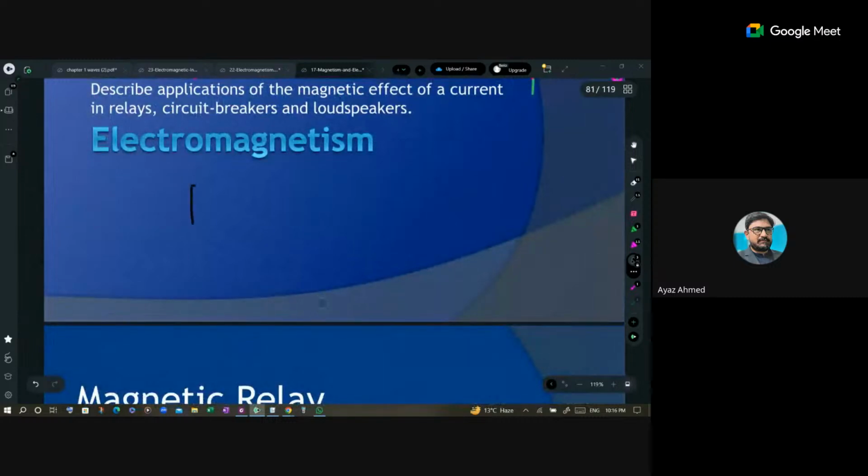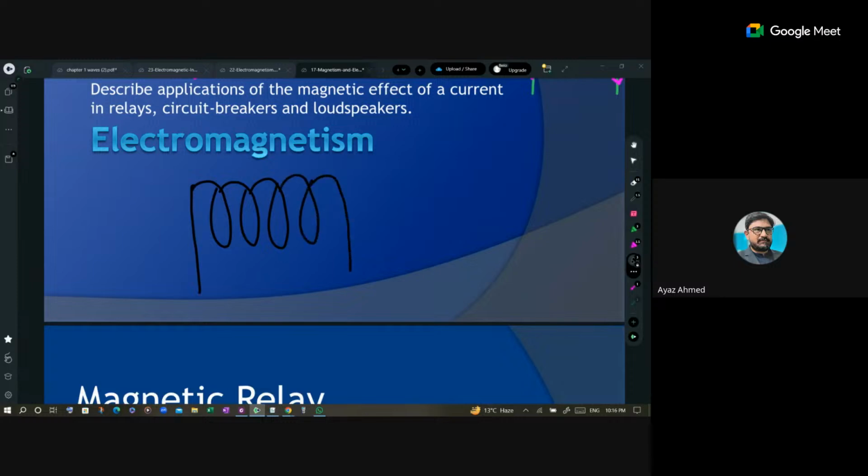Right, let's say I'm going to prepare a coil, and then I will be winding up this lesson today. This is the positive and negative pole. If I say that current is going in this direction, then on all these front edges the current would be in this way. So you grasp the coil with your right hand. This end becomes north and this end becomes south.